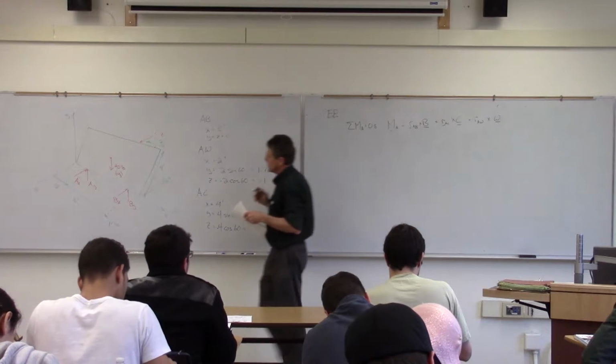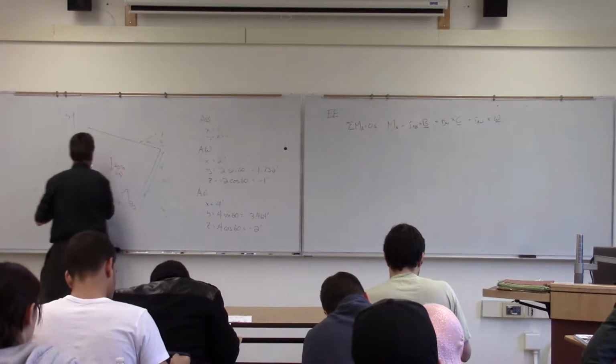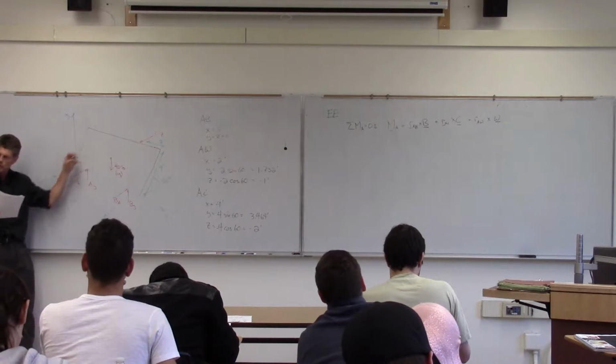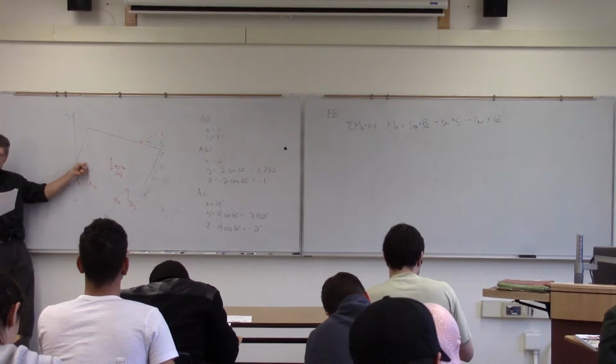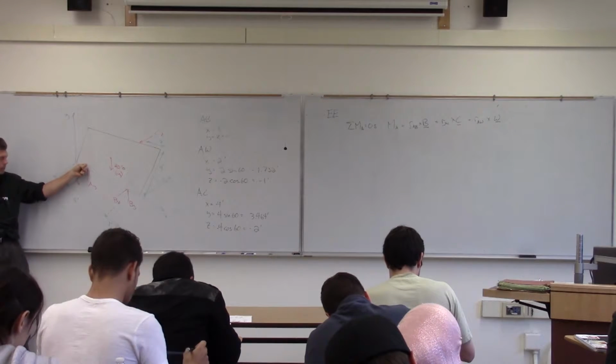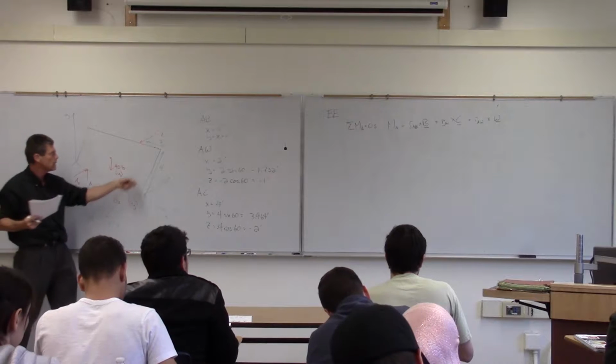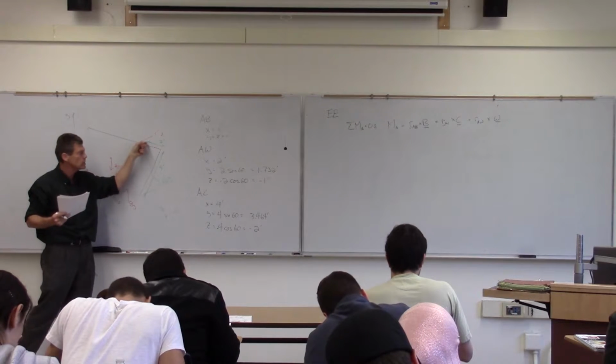So that's what I'm going to do then, is I'm going to take my moment equation and I have to include all of the forces, because I'm taking all of these forces, moving them out of their lines of action and moving them here to create a couple. So I've got my 40, my 2 components of B here, and my 1 component of C here.